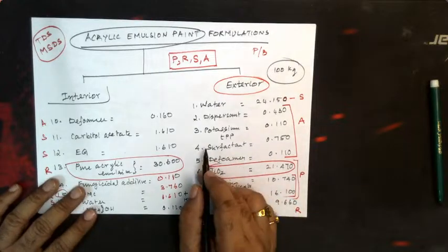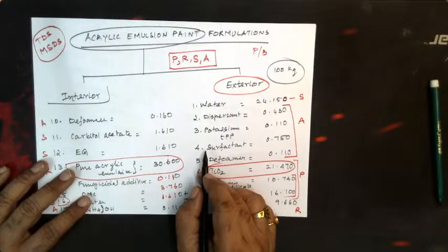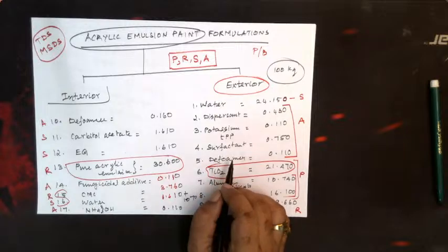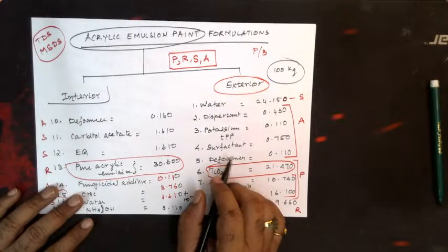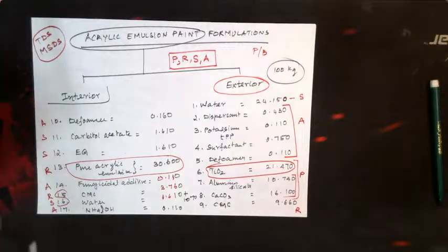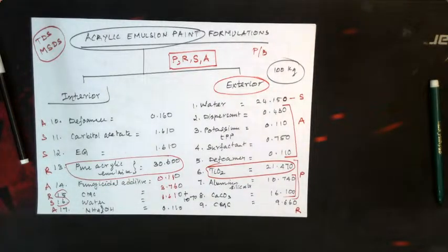Why do we add this surface active agent? Because the pigments are a fine powder. The wettability is a tricky issue here. So in order to make the wetting of this pigment proper, we need to add this surface active agent. Then during the process, it should not result in any heavy foaming, because we are dealing with the emulsion. Emulsion is nothing but a soap. So soap will definitely give some lathering. So it should be free from lathering, otherwise it will disturb the system.